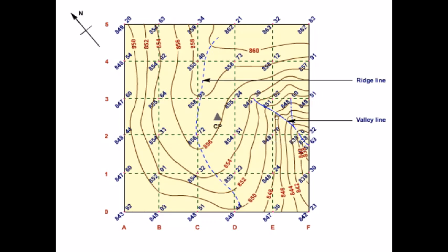So you have these distinct inverted V shapes, and over here, this represents a ridge line, because as you can see, the elevation keeps on decreasing on successive contours, and every contour has a distinct U shape at the center, and they coincide basically. So whenever you get a shape like this, that means it's a ridge line. And we discussed before, what is a ridge line? A ridge line is the top of a mountain peak, or it is in continuation in this case.